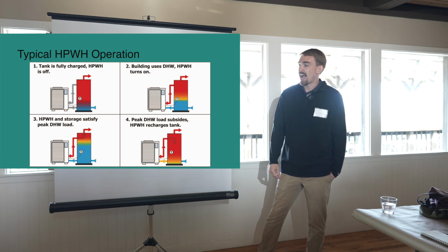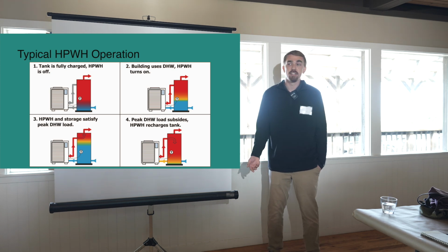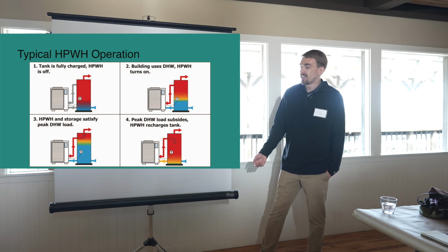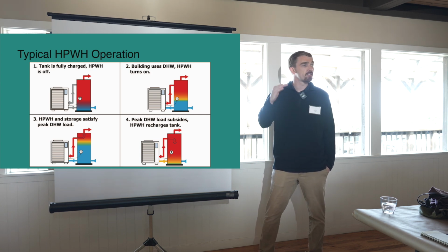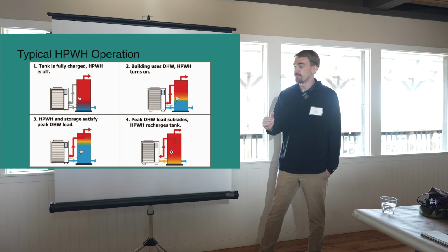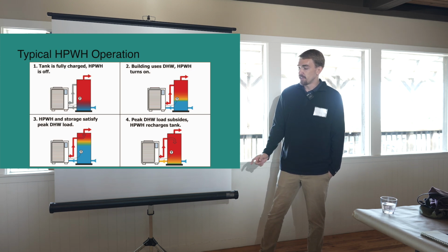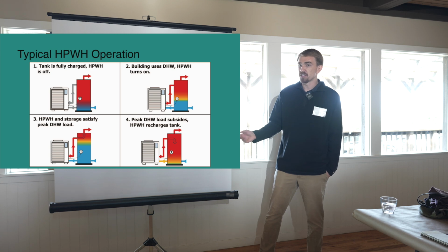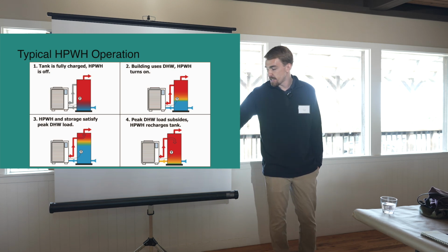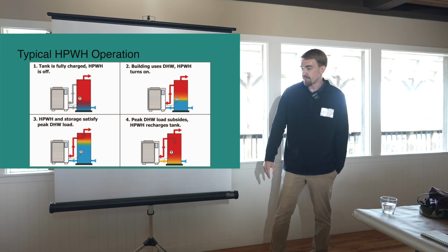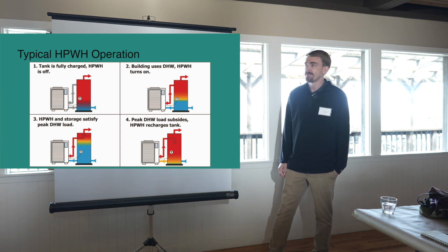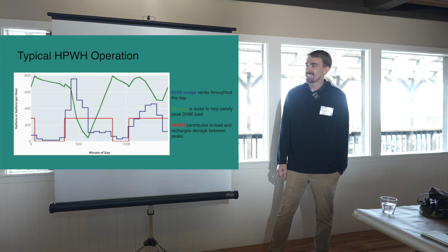And then after our load subsides, after everyone's done with breakfast and dishes and has gotten out of the showers, that's when the heat pump can keep up and trickle charge this storage tank back to full. So after that sensor gets hot again, or maybe if our controls are one step fancier, we'll have an off temperature sensor down here. After that sees warm water, the heat pump's going to shut off and it's ready for the next peak. Let's go ahead and next slide, please.